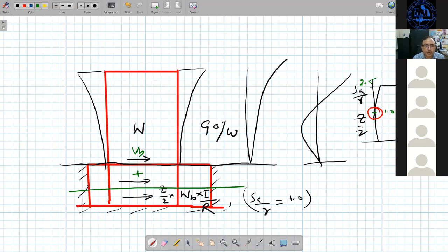In that case, you should go for time history analysis. First of all, you should look at why you are not getting 60% mass. Is there any irregularity in your building? Then you should take care of that irregularity. If that irregularity is not allowed by the code, you should correct it. And second, you should go for time history analysis in that case.